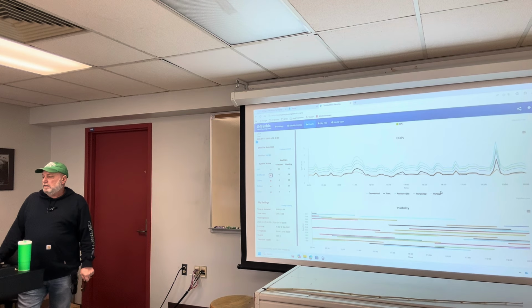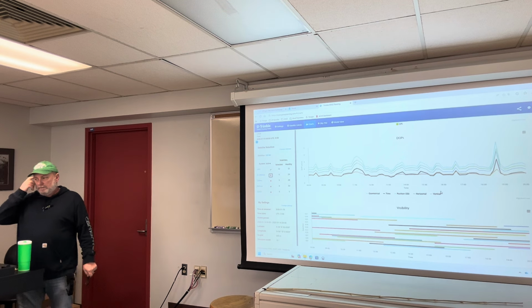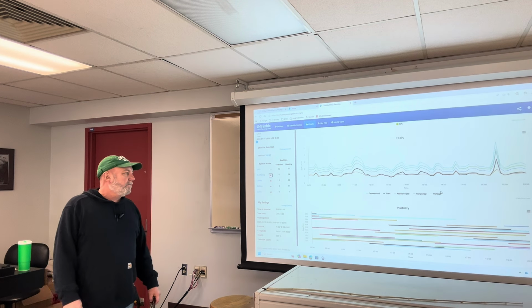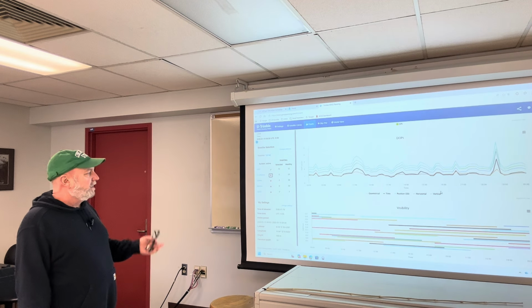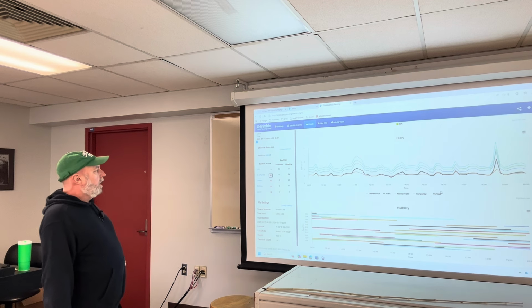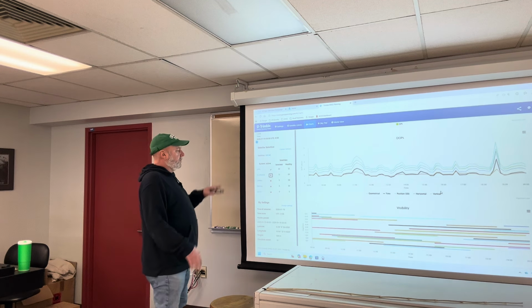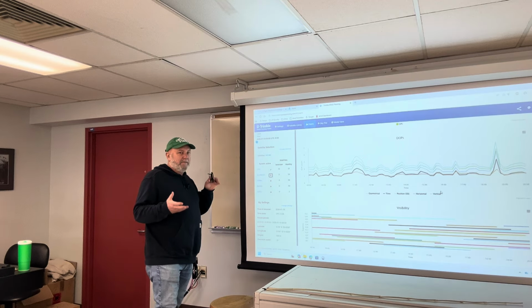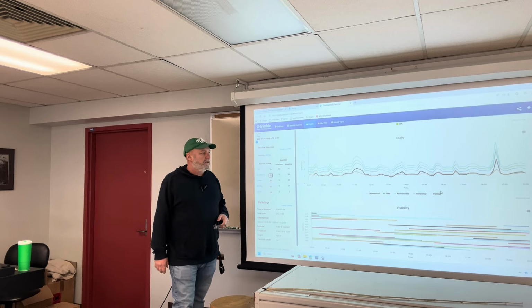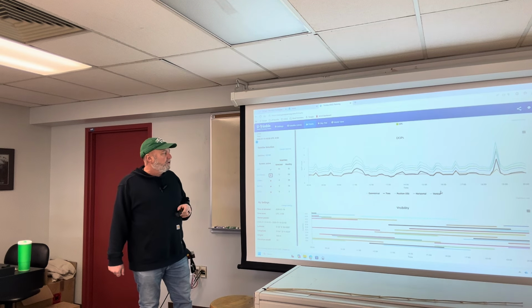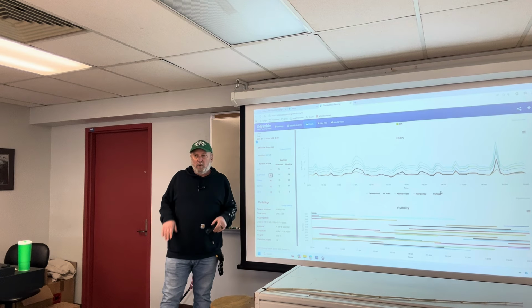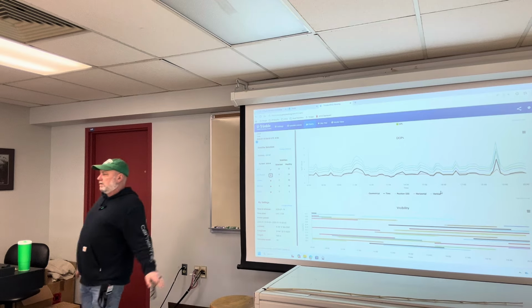Here we can look at the difference in the DOP values. We can see they're color coded. We have the geometric, time, position, horizontal, and vertical, so the GDOP, TDOP, PDOP, HDOP, and VDOP. Again, this is kind of a unitless factor. Anything below 2 is supposed to be exceptional. Anything between 2 and 4 should be good. 4 to 6 is questionable. Anything above that, you definitely want to ignore.